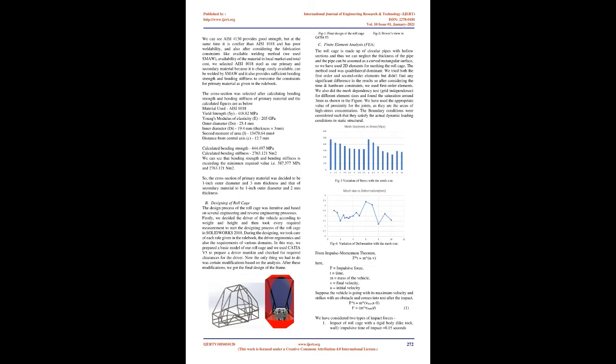3. Methodology. Finalizing the design was an iterative process. Steps included in the process: 1. Preparation of basic design. 2. Calculation of boundary conditions. 3. Analysis of the design under calculated boundary conditions using the finite element method in ANSYS software. 4. Optimization of design based on results obtained from the analysis. 5. Again, applying steps 3 and 4 on the optimized design. 6. Repeating the process to get the desired design.